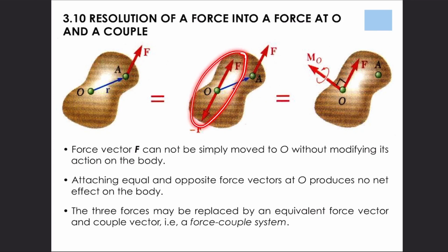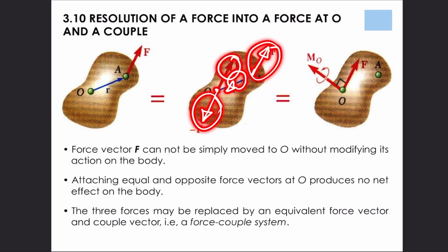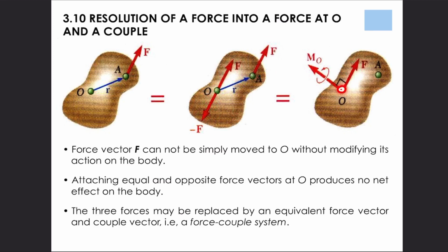But if you add these two equal and opposite forces, this force and this force will now be a couple with its direction of rotation in this direction. So now we have a couple and a force at point O. So it can be resolved into a force, this one being the force, and this one being the moment.